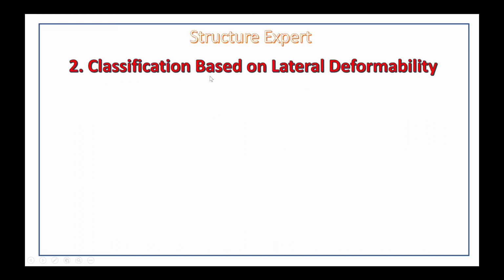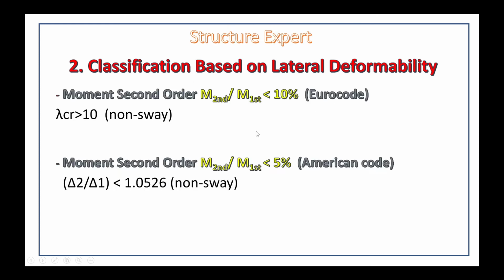Now we continue to classification based on lateral deformability. Now the moment second order effect M2 over M1 is lower than 10 for the EUROCODE, and critical lambda is over 10. This structure is non-sway or flat frame. In Europe, they call it flat frame.